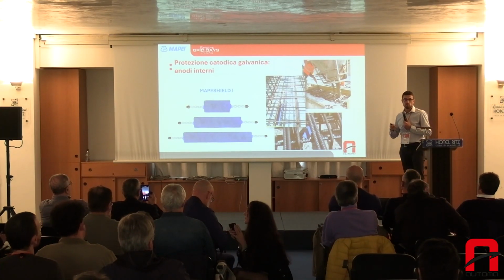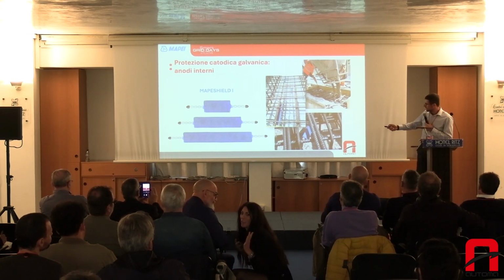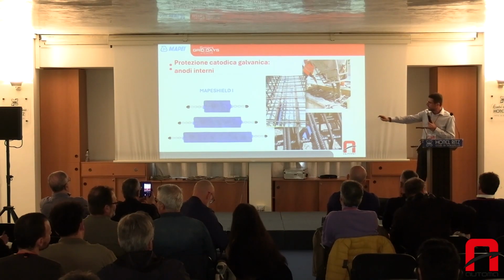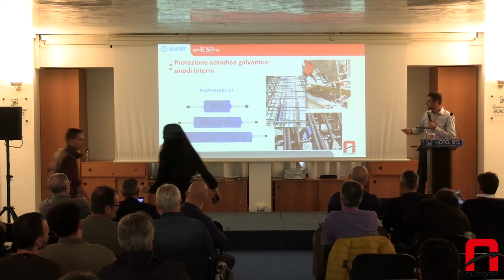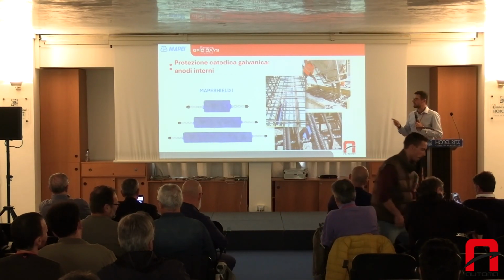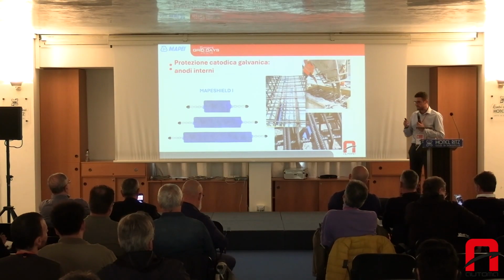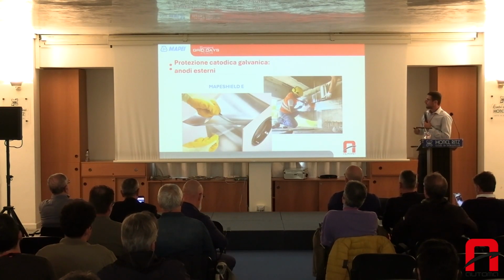The installation is very simple. It does not require any kind of specialized skill. As you see here, you simply have to fold the terminal parts of the anodes on the reinforcement bars, and then you use a metal thread to make sure that the anode remains in position.